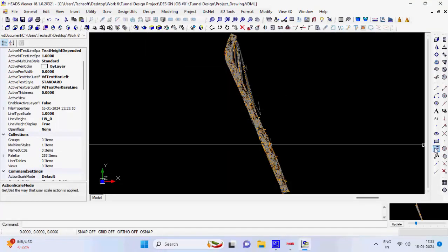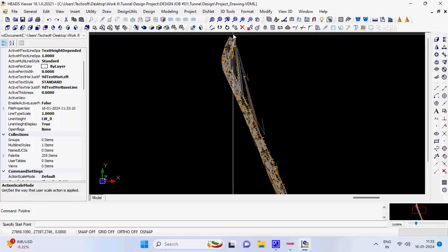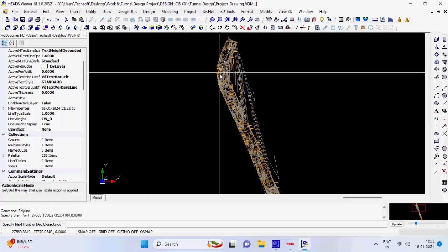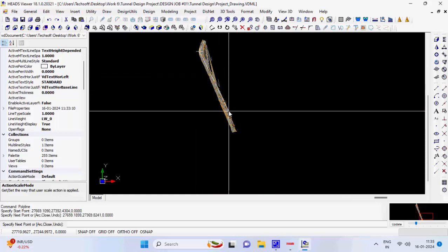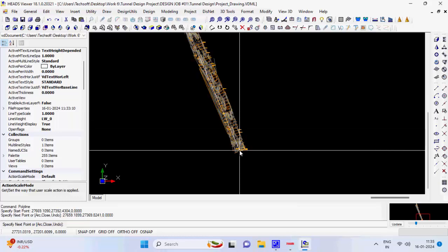Select item polyline from menu Draw and click the points by following the turns and bends of the ground model. Please note that the points must not be clicked very close to each other, as this will result in overlapping of curves which are to be assigned at these points. These points are horizontal intersection points, HIP. Click right mouse button to terminate the polyline.